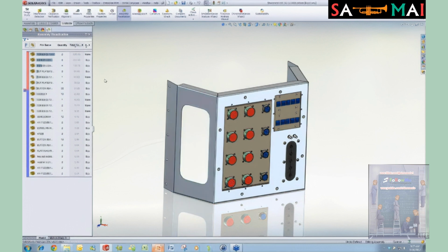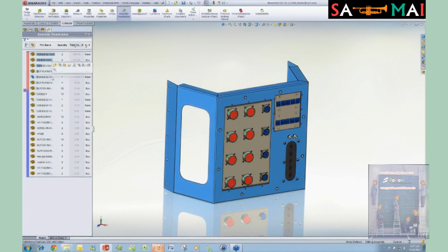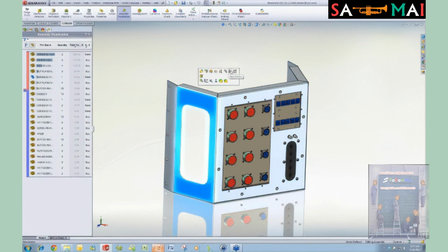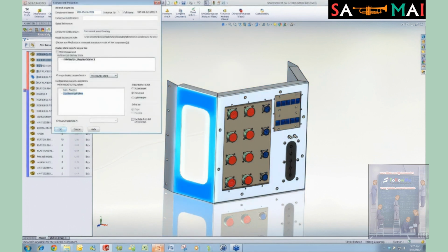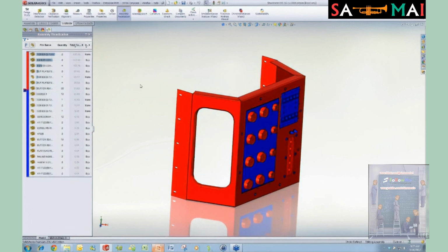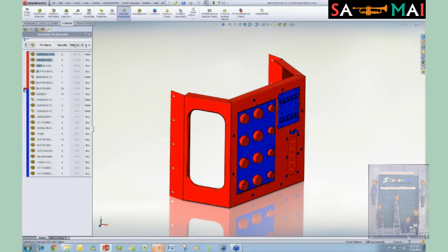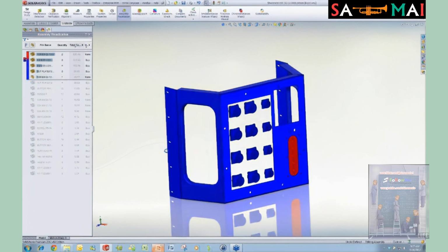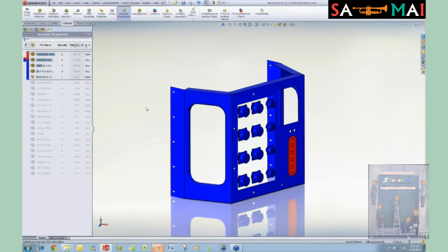So I have this one part, which is right there, and it's showing that configuration. If we switch to the other one, it's got a different cost, $59 applied to it. So I can add in all my different costs if I want to, and I can color code that with the assembly visualization. So if I put costs in here, we can see what the most expensive parts are. So I can change this timeline, kind of drag it up there. Say I want to see everything that's more expensive than $59. Hides everything else, and there's everything that's above $59 in price.